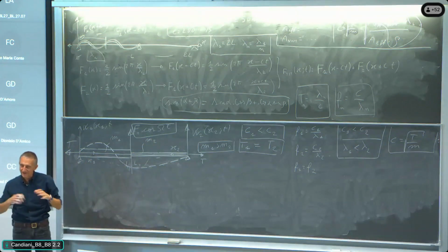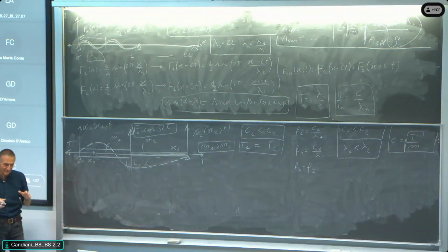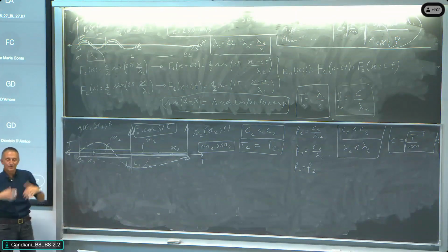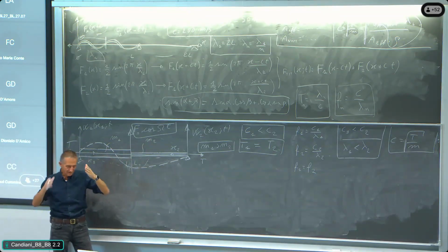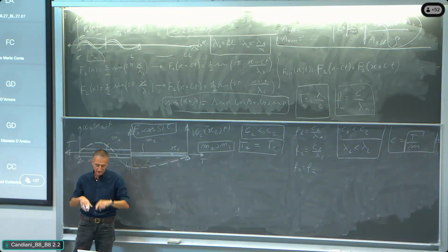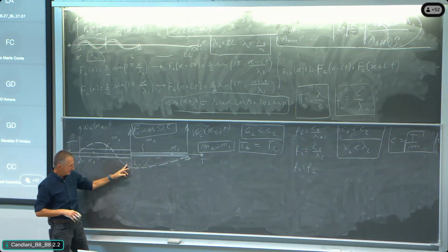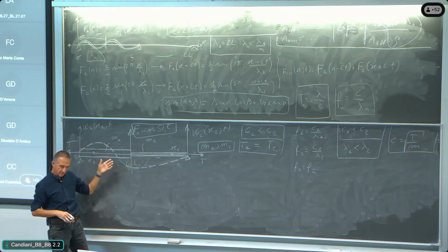Right? The purpose of all of this is to play with this piece of code, recognizing that moving the frequency, you are getting into a situation where the amplitudes are jumping up to infinity, and the shape is becoming equal to the shape of the specific mode of vibration that is being excited in resonance.